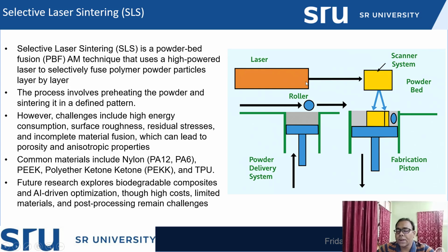Similarly, when the laser light passes, it will scan the given area in which the part fabrication is required, layer upon layer. The laser will scan only those areas, not the entire surface area, because on the powder spread on that surface, only some area needs to be manufactured. So the laser scans those areas only, and the laser beam energy is transmitted to the powder, and the powder gets heated and finally is partially melted.